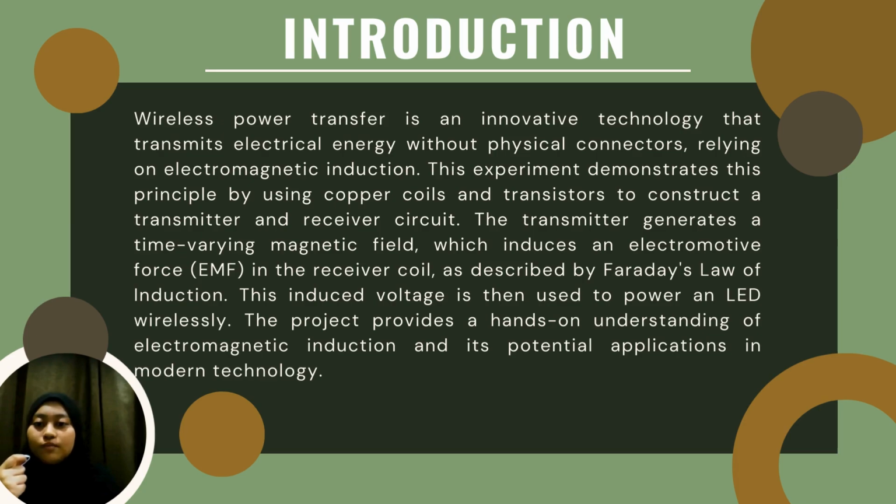So for the introduction, what is wireless power transfer? Wireless power transfer can transmit electrical energy without a physical connector, relying on electromagnetic induction. In this experiment, we use copper coil and transistor to construct the transmitter and receiver circuit. The transmitter generates a time-varying magnetic field that induces an EMF in the receiver coil, as described by Faraday's law of induction. This induced voltage is then used to power an LED wirelessly.